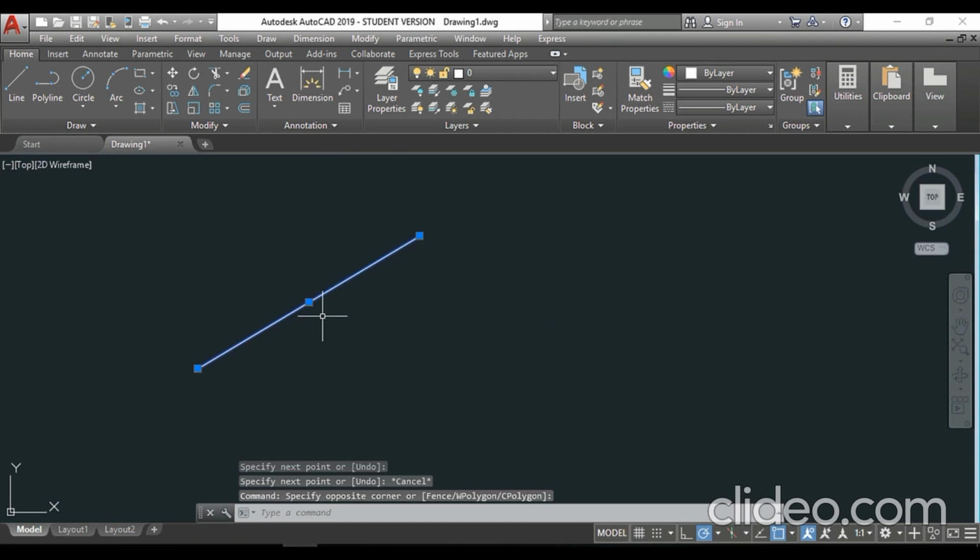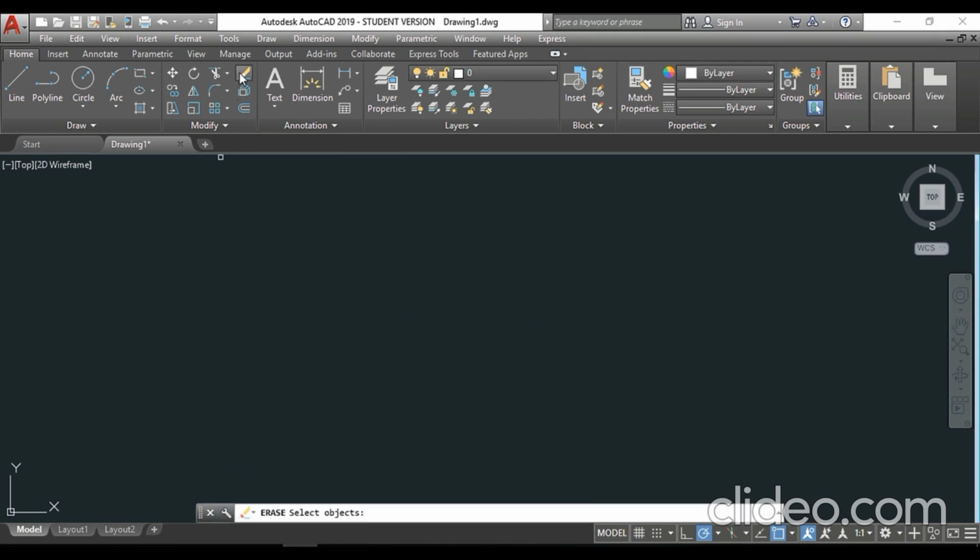The command bar specifically helps you identify which command is activated at a single point in time. When we click on the erase function, we see that erase is activated on the command line. When we click on the rectangle function, the rectangle function is activated, and many other subsidiary functions are shown in the command bar. Pressing the escape button clears the screen and the command bar.